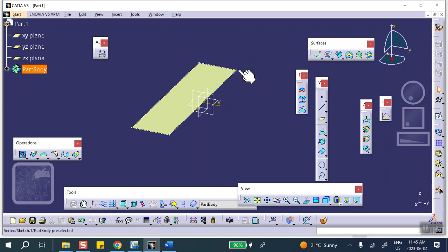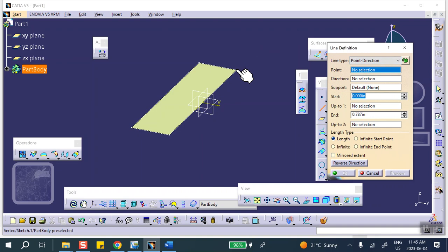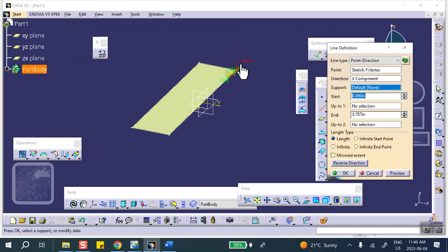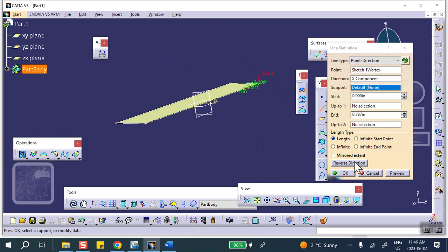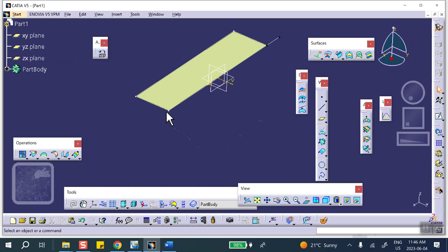Okay. So one option for making these beams is obviously you need lines here. So I'm going to make my lines like this. Make a line starting from a point and a direction. The point is this point, for example, and the direction is direction X according to what I have here. This is going that way if you look at it. So I want it to go to the other direction, and I want it to go at the length of 1 inch. There we are. And I repeat this thing on that side.